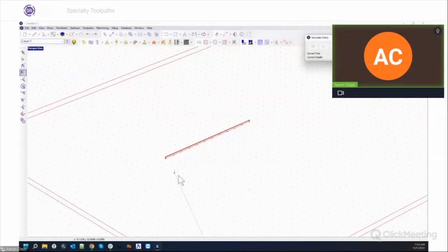So you'll see our tool approaching, plunge, make the cut, come back, and then retract out of the same hole. This is useful for all sorts of things. I've seen people use it for creating keyhole style cuts where you have a bit that can cut down and then you want it to move forward and then come back. Or perhaps you're doing some kind of cut in the side of a piece of material, like for a door or something, that's going to have these little tabs so that when you glue them together they meet.